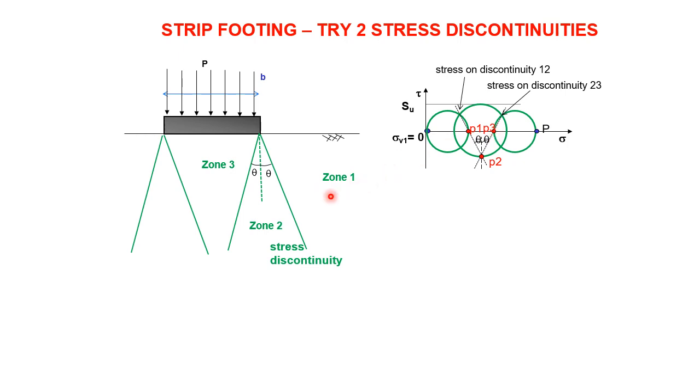How do we get it? Well, for the Mohr circle on zone 3, we consider the stresses that we know, which are these ones here. And from the stresses we know, we project down that same line that we had before, and where it intersects the Mohr circle must be there. So, for example, the vertical stress, P, acts on a horizontal plane. So again, the horizontal plane will go through the same pole, which it must do.